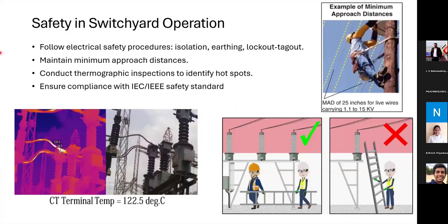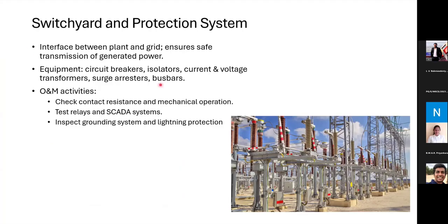And regarding safety in operation and maintenance, there are quite frequent operations. In Sri Lanka, I forgot to mention, one of the main aspects of protection in switchyards is clearing out bird nests, because in these gantry structures it is pretty common for birds to have their nests.